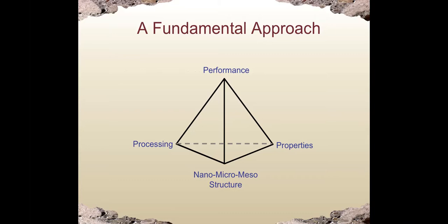Right. So to achieve the design performance, either high durability or high strength, the fundamental approach is based on what type of performance we want to achieve. We need to focus on the properties of raw materials, what type of raw materials we use, including admixtures. For example, fly ash, silica fume, chemical admixtures such as superplasticizer. Sometimes special processing technology, such as using high pressure or heat, or even extrusion, can also be used.